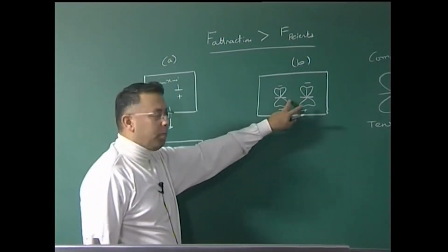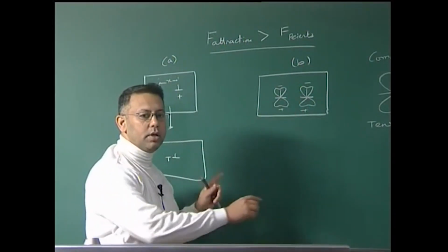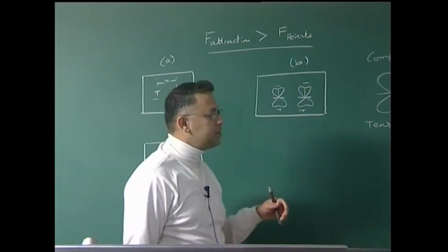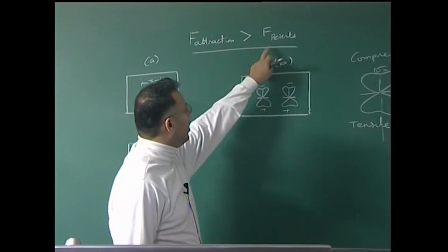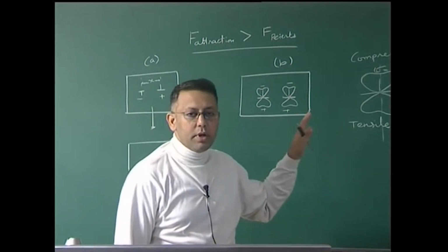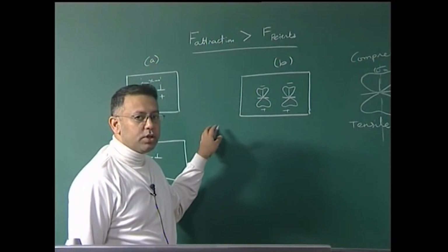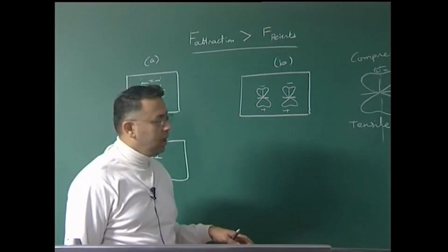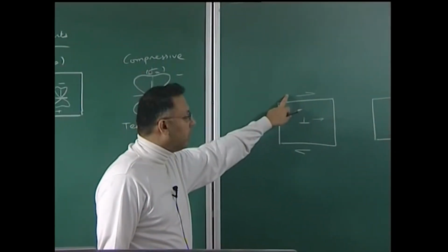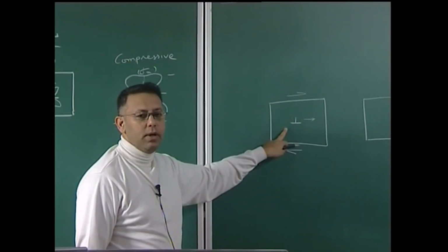And similarly, if the repulsive force is larger than the Peierls force or the Peierls stress, then automatically the dislocations can move farther apart, till of course, the repulsive stress becomes lower than that of the Peierls stress. Therefore, when I am considering pairwise interactions, these defects can talk to each other via the long range stress fields. And additionally, we have to also worry about the external stresses or external constraints which have been imposed on the system and their effect on the evolution of the defect structure.